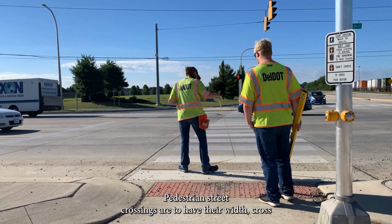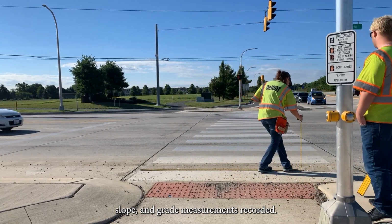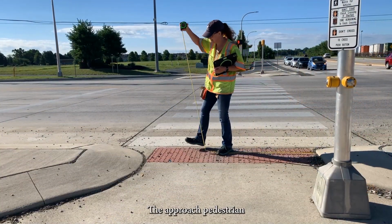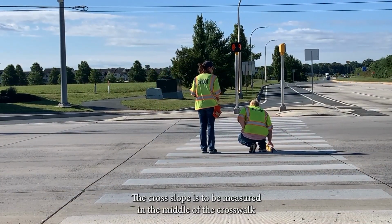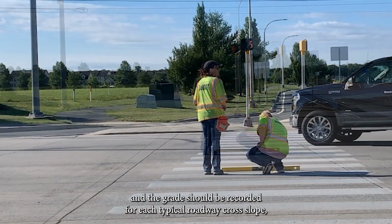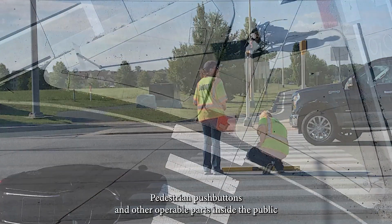Pedestrian street crossings are to have their width, cross slope, and grade measurements recorded. The approach pedestrian access route width is also to be recorded. The cross slope is to be measured in the middle of the crosswalk, and the grade should be recorded for each typical roadway cross slope which the pedestrian street crossing traverses.